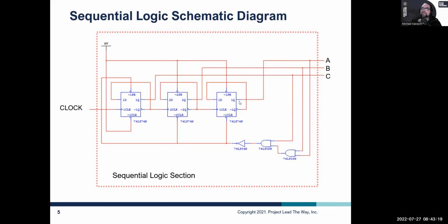That means as high as we could count with this little guy right here would be 1, 1, 1 in binary. If we bring up our little chart here, 1, 2, 4, so 1, 1, 1 would be 4 plus 2 plus 1, or 7. 7's as high as we could count with 3 flip-flops. But that works for us, because we don't have to count beyond 7, since this thing is designed to go from 1 to 6. So we don't need any more flip-flops.